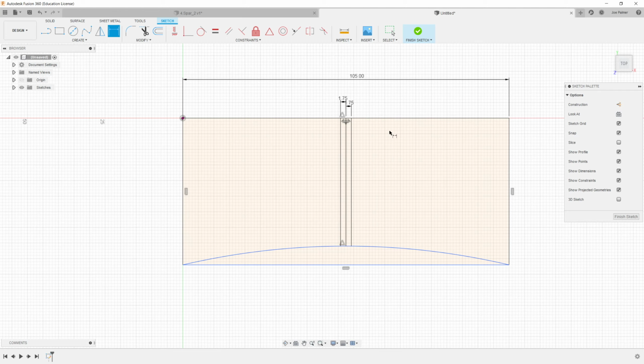Okay, now if I look back at my sketch, I know that the length of this center line is 45 millimeters once I've taken into account the 2.5 millimeter border running all the way around the edge of the component. So I can get my dimension tool again, and I can dimension the length of this center line, and I know this is 45 plus 2.5 plus 2.5.